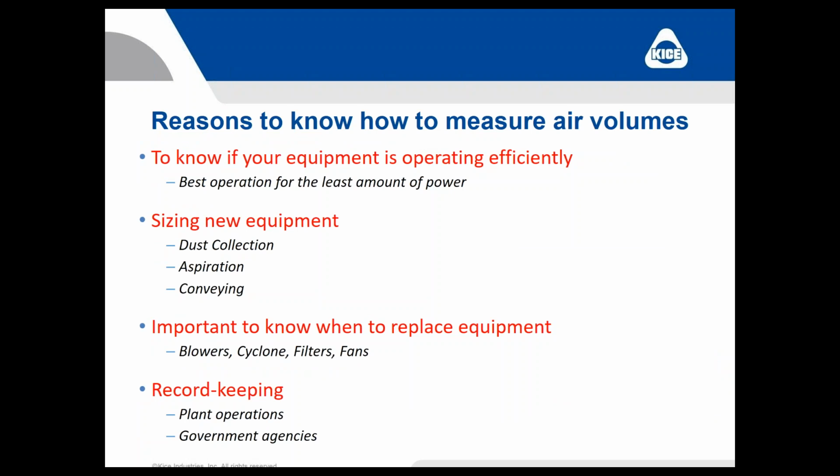Reasons to know how to measure air volumes and reasons you need to know why and what the air volumes are. It's to know if your equipment is operating efficiently. It's trying to get the best operation that you can for the least amount of horsepower, or at least not waste a tremendous amount of horsepower these days. Sizing new equipment. You have a new facility or you're changing your facility, you're adding dust collection. How much air do you need? How much aspiration do you need? How much air do you need for conveying? All these reasons for measuring air volumes and helping to determine air volumes can help you in sizing new equipment.